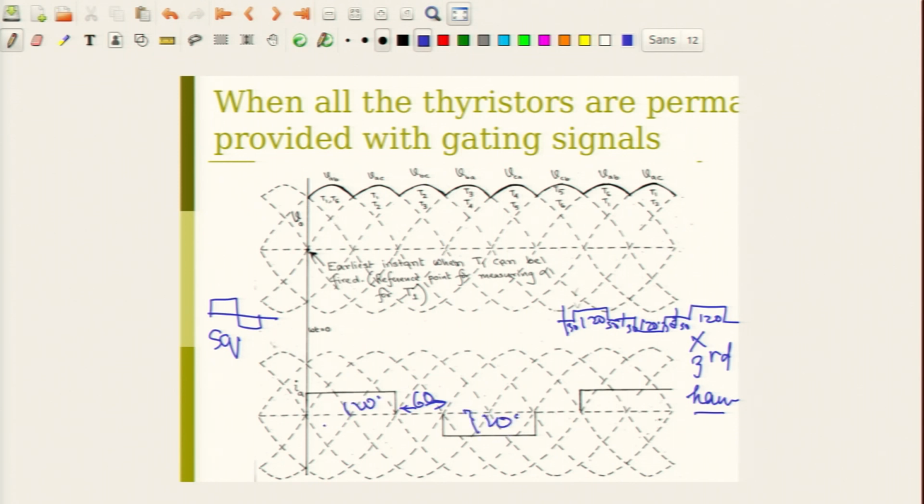And in fact, if you look at this waveform IA, the fundamental component of this waveform, if you use a Fourier series and compute the AN and BN terms, that is the cosine and sine terms, and redraw only the fundamental component of the waveform, it will have a waveform like this. It goes down to here and then like that.